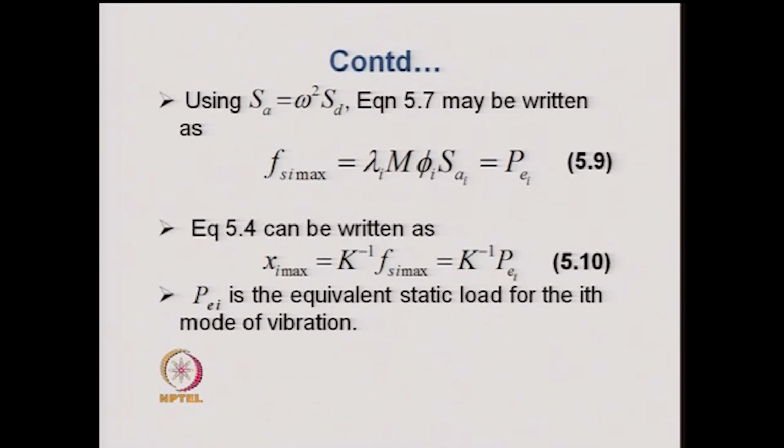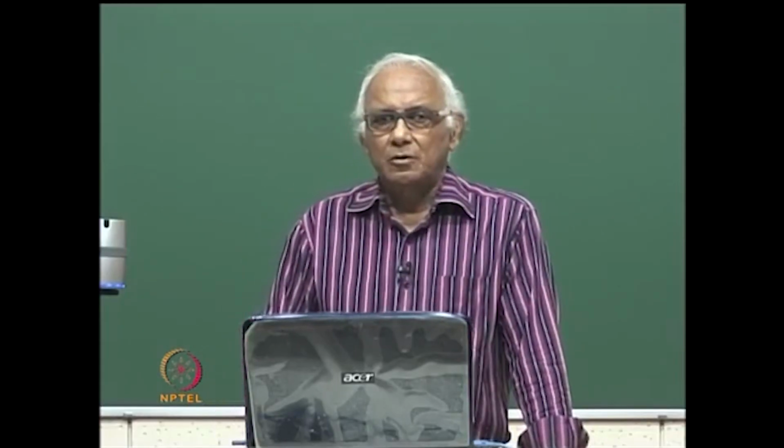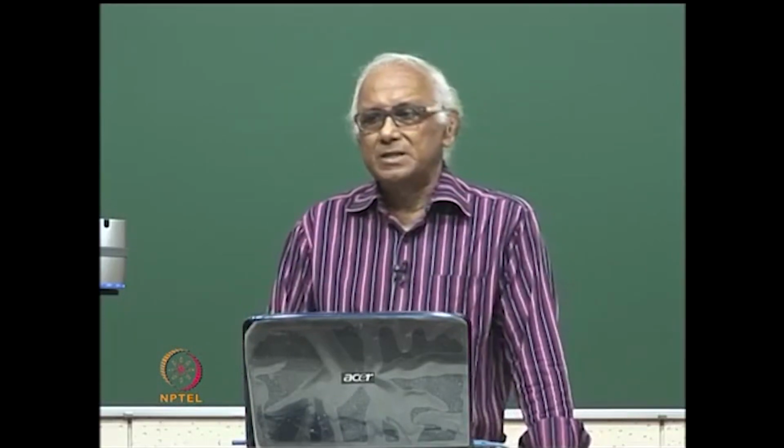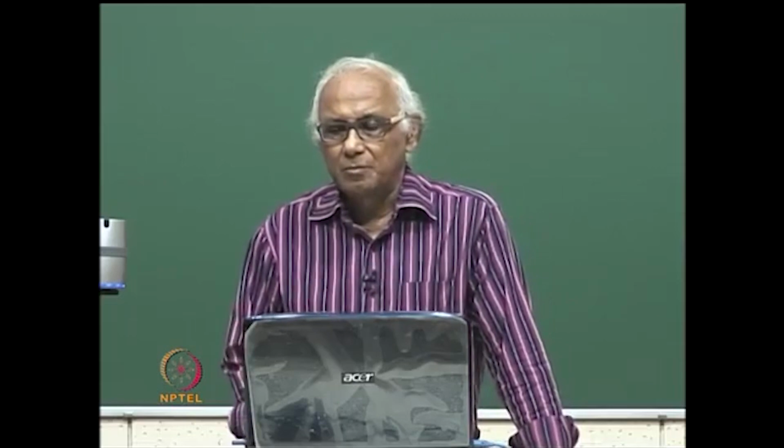And the analysis that we perform in equation 5.10 is purely a static analysis. So, therefore, we see that in finding out the equation 5.9, we step by step follow the normal mode theory, come to a single degree of freedom equation, and for that single degree of freedom equation one can find out the maximum displacement of the structure if it were vibrating only in that particular mode.